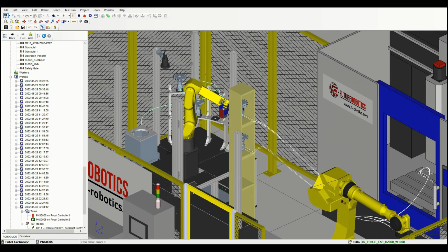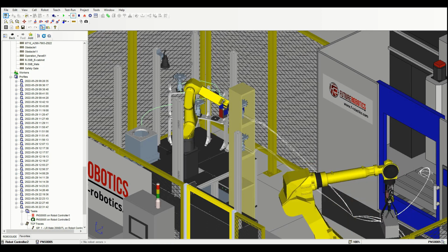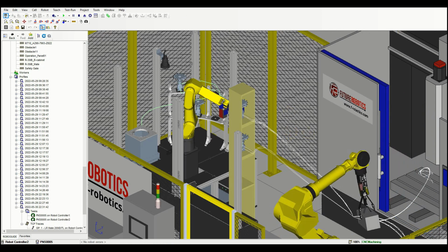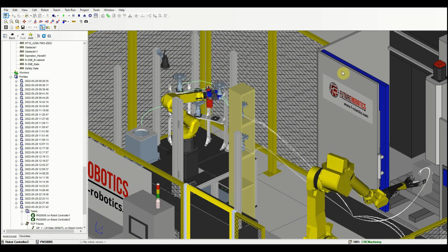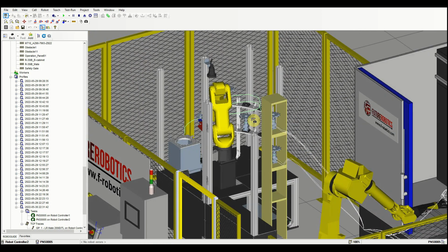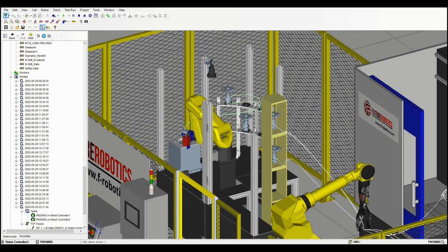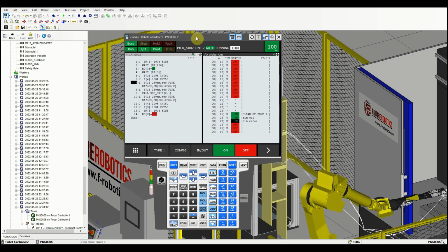So now let me take that fault away, and I'm going to enable the collision zone on the other robot. So this time when we're going to pick from here, we're going to also fail, but we're going to have the collision zone on that will prevent this robot from picking. So let me show you how this actually looks on the robot side.